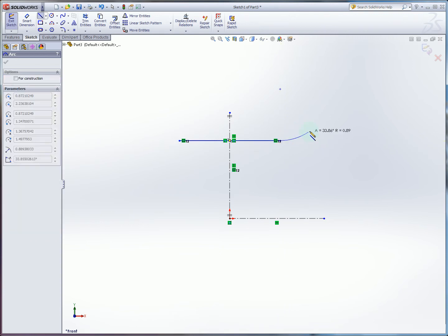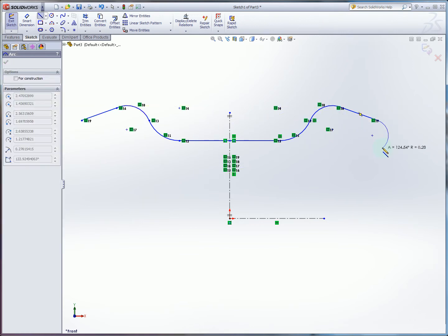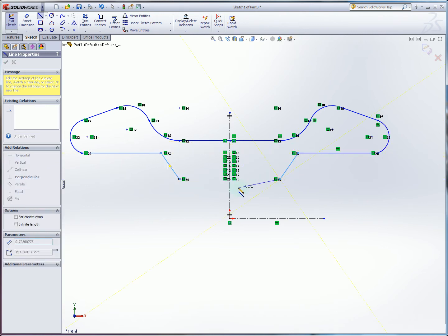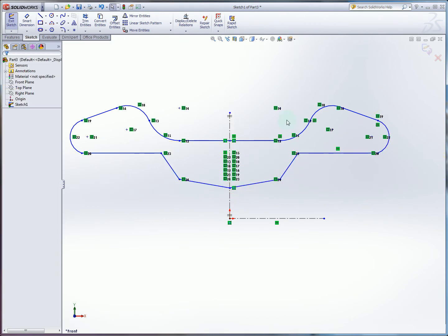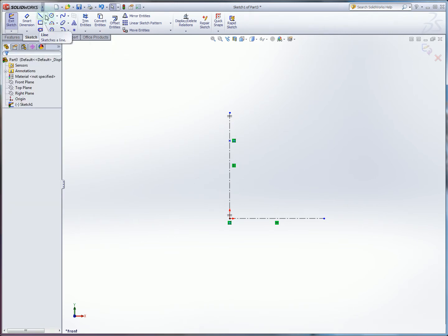You can also, by hitting the A key, toggle to tangent arcs, which is very useful if you're drawing basically the equivalent of a polyline in AutoCAD. This lets you draw a line or a smoothed feature. Very, very quick and easy. The line feature is just those lines and arcs, but with those two tools you can do 80% of what you need.